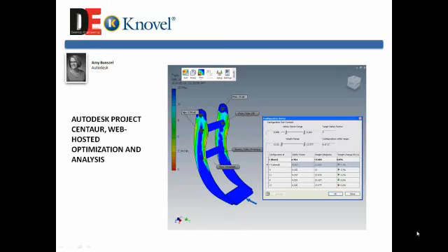So, and again, if you've added constraints, if you said, due to some design rule or company practice, this part should never be less than half a millimeter in thickness or diameter, and if you put in that modeling constraint and tried to decrease your geometry beyond it, the system would not let you do that. Versus, if that intelligence isn't built in, if you don't have those constraints, if you don't have equations, the modeling system would let you make any change to the geometry without giving you an error message or asking, do you really want to make this change? It's violating something that you told me to do earlier.